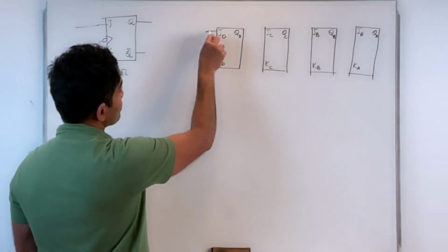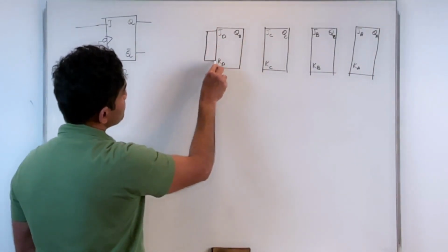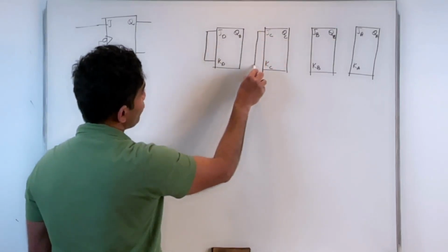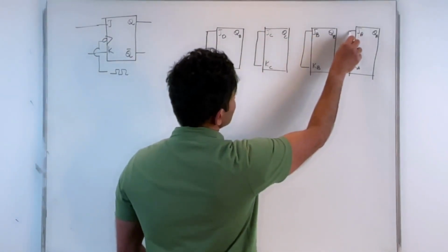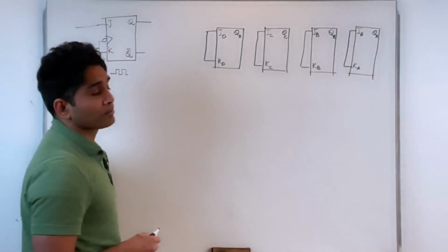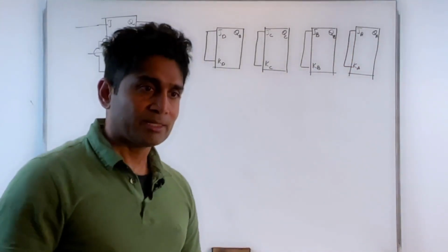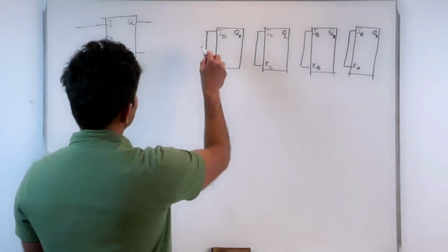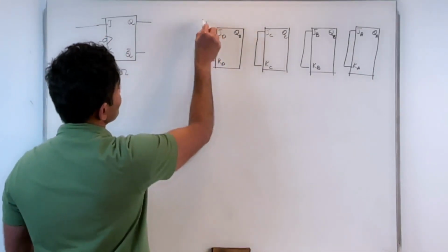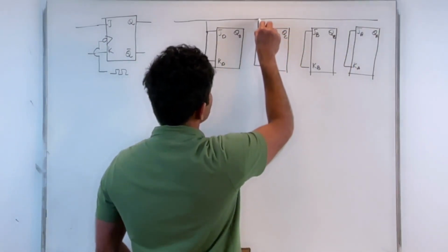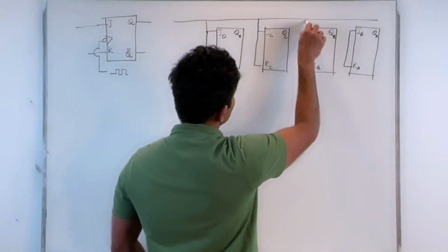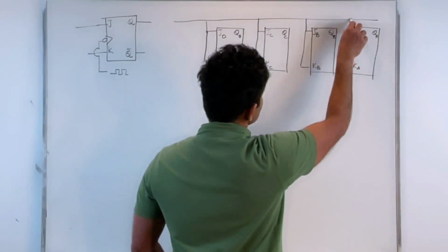And what I'm going to do now is place each of these flip-flops in the toggle state. The way I will do that is by shorting the J and K inputs and applying a value of 1 on my J and K values, right? That configures each of these flip-flops in the toggle state.